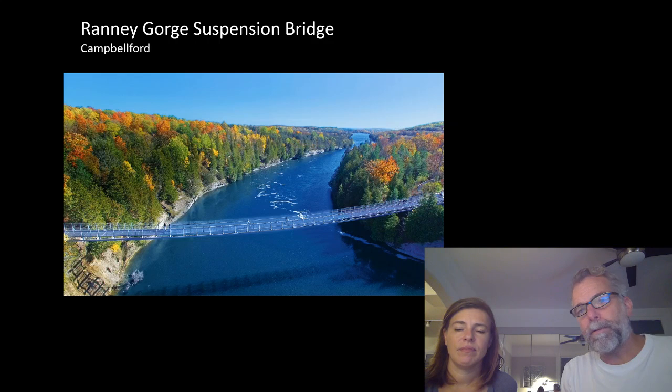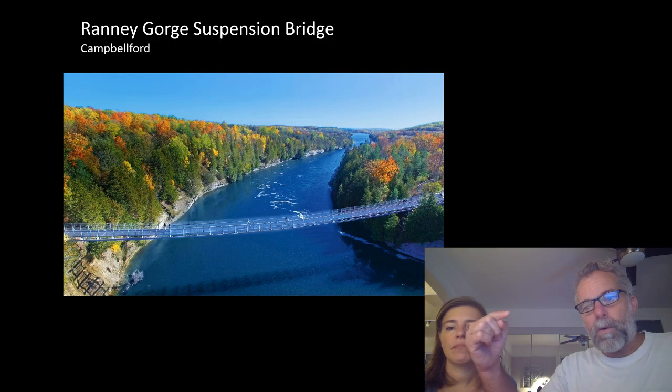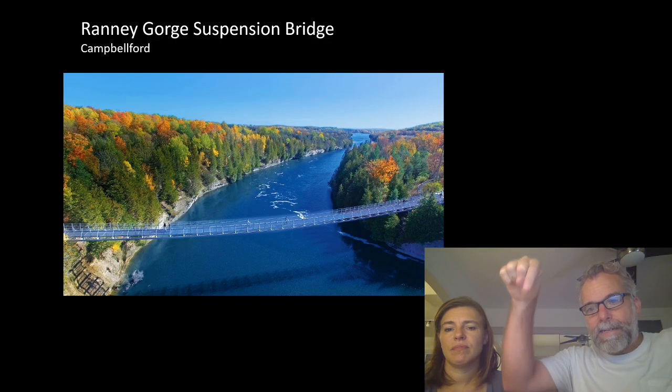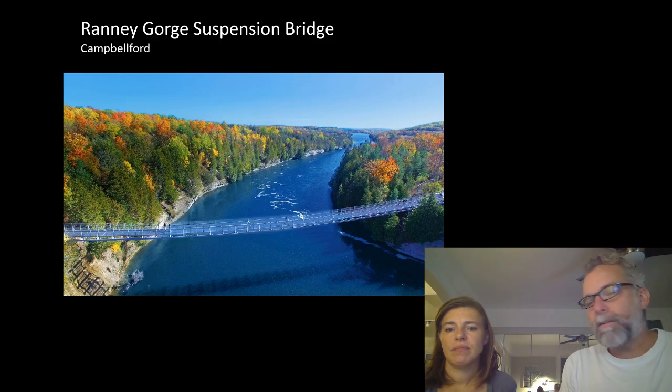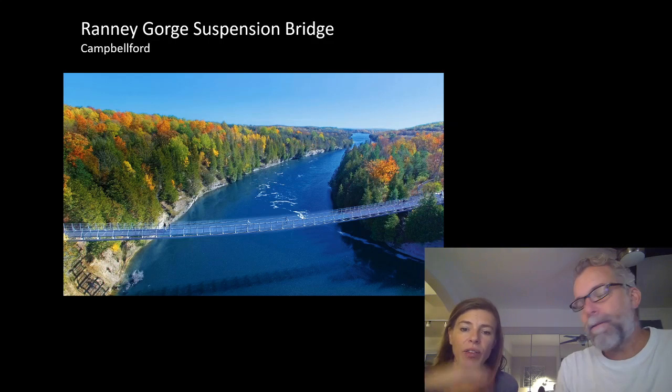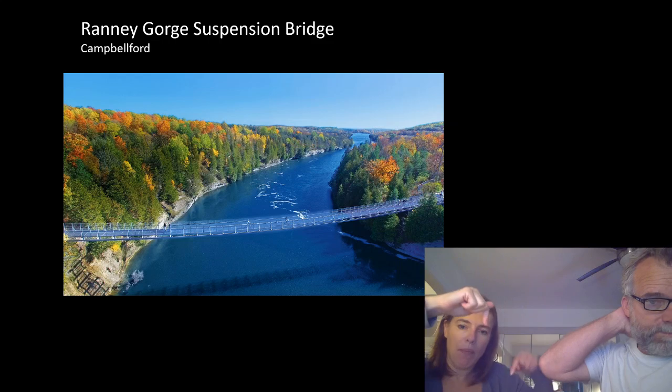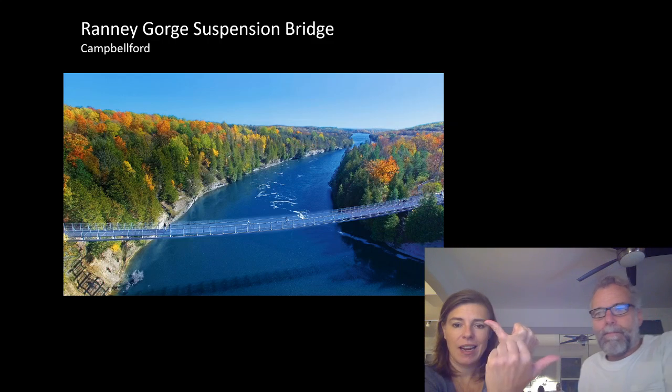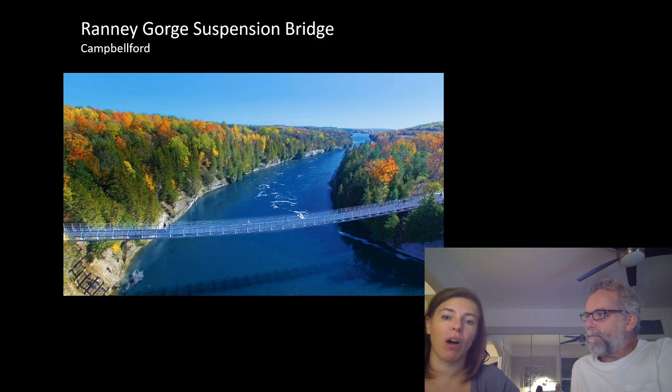because that's the maximum permitted slope for wheelchair access. So it's probably 1 to 20 is the steepest angle. What that means is that the horizontal force is 20 times the vertical force. So the horizontal force at the end of these things is gigantic. So take whatever your load is on it, multiply it by 20, and that's what you're trying to pull out of the rock.